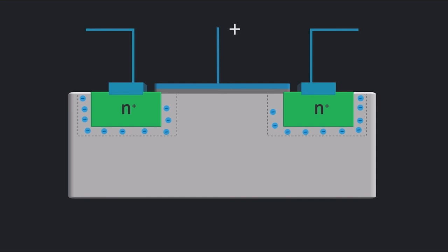If you increase the gate voltage, that positive voltage will repel holes in the substrate away from the area between the source and drain, an area called the channel region, a physical region. As the free holes leave the channel, only negative fixed ions are left, creating a depletion region across the entire channel. Besides this depletion region, an inversion layer of electrons starts to form at the source, and as the voltage increases, that inversion layer expands toward the drain.